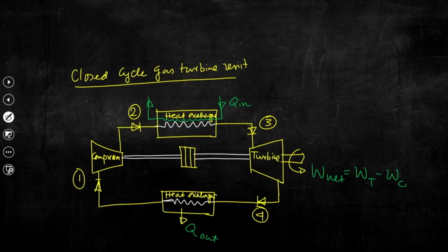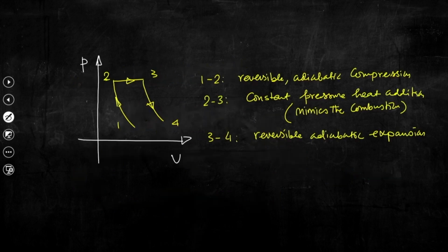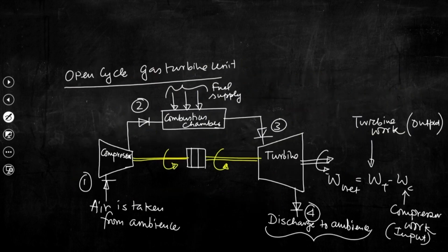This is a constant pressure heat addition, not only at constant pressure. In reality, in real application, there is basically combustion, and because of this combustion we are trying to discuss here using a simplified schematic diagram. So, the combustion process is mimicked here by an equivalent amount of energy addition at a constant pressure and constant Cp.